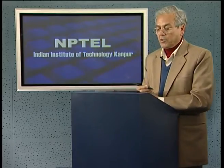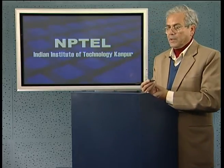we will see that it will be convenient to consider the dynamic problem after we convert the dynamic problem into a static equilibrium problem. What I mean to say is this, that any system under motion, in general motion, if it is in dynamic equilibrium, it means that it is running under the influence of some forces. Then each and every member of the mechanism will be subjected to some forces which are acting on it and which are producing the resulting motion parameters like accelerations, both angular and linear.